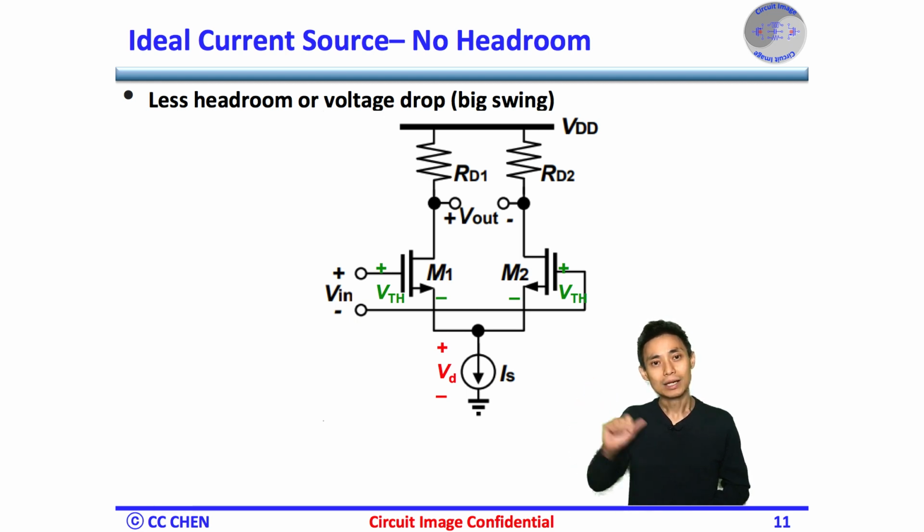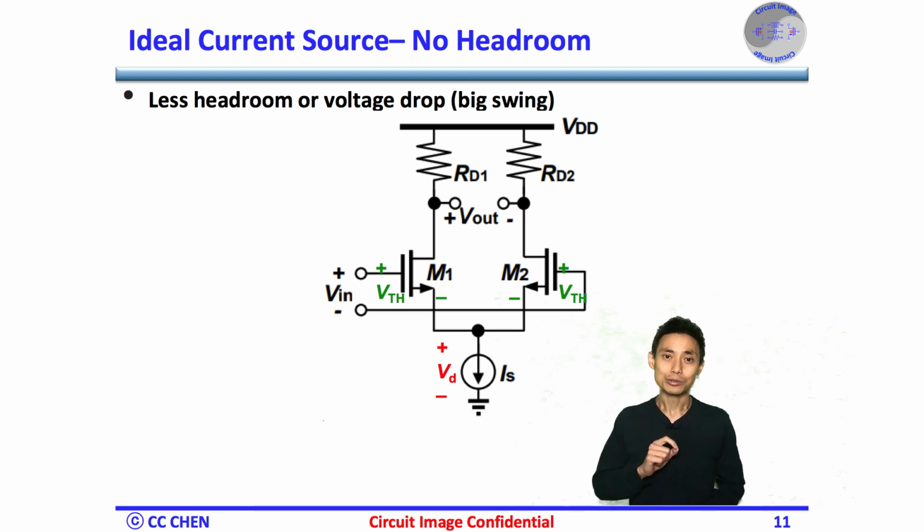would be limited. The amplifier's goal is to boost the signal-to-noise ratio and then reduce the bit error rate. Therefore, increasing the signal swing is the goal, but adding the current source would decrease the signal swing if the voltage drop across the current source is too much.